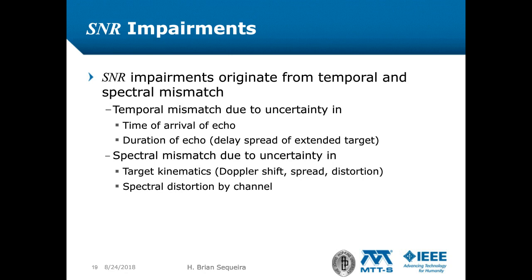For the time being, it is sufficient to note that a mismatched receiver will have nulls displaced from that of the signal, and therefore sample noise and suppress echo energy because of that displacement. The SNR is thus impaired.